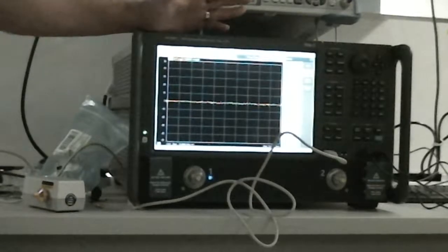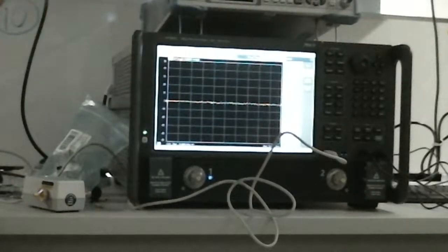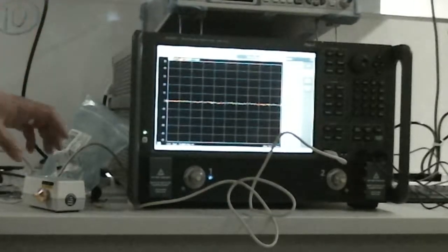There's a very nice chart that details the signal-to-noise ratio you need relative to the uncertainty of the measurement, and it says about 0.1 dB is relative to 29 dB of signal-to-noise ratio. So 60 dB plus 29 dB of signal-to-noise ratio means I need 89 dB of dynamic range, right? That's why we would use this narrower IF bandwidth, because we want to make sure that we have really good dynamic range in our measurement.